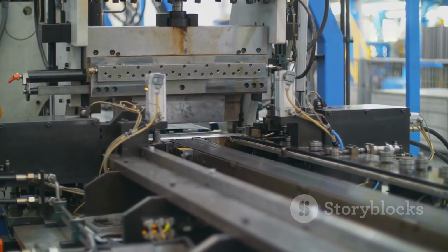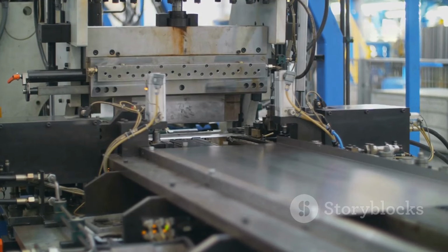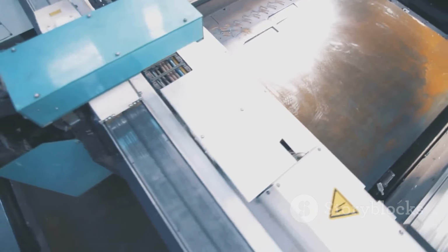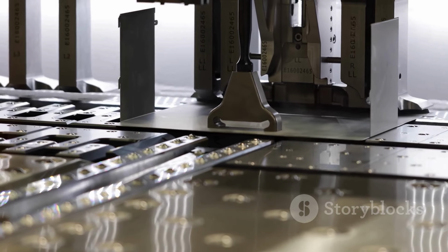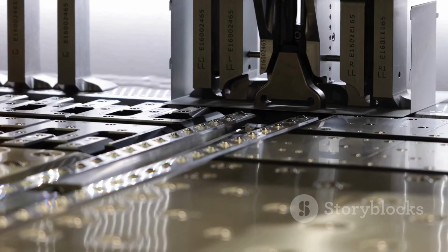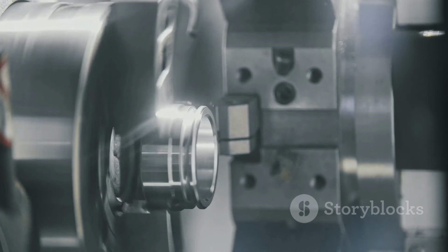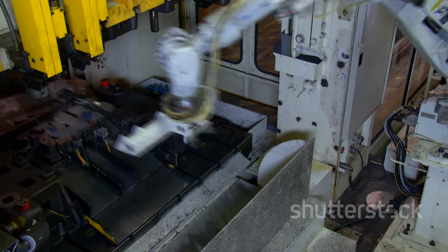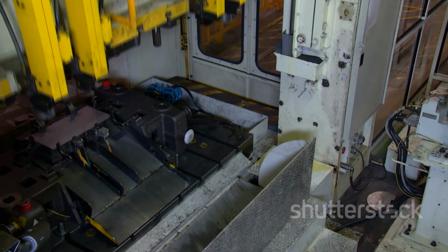First and foremost, always design with manufacturing in mind. Consider the tools and processes that will be used to fabricate your parts. Avoid overly complex geometries and tight bends that might be challenging to achieve. Keep your bend radii consistent whenever possible. This simplifies the manufacturing process and reduces the risk of errors or distortions.